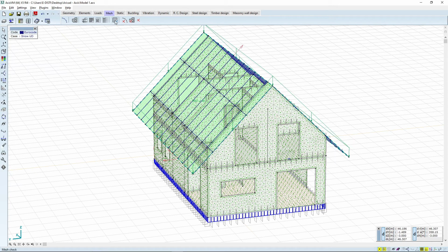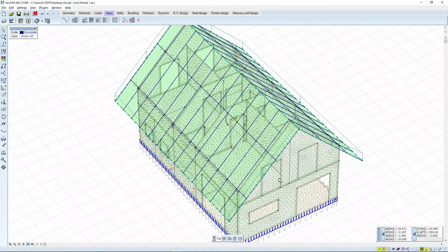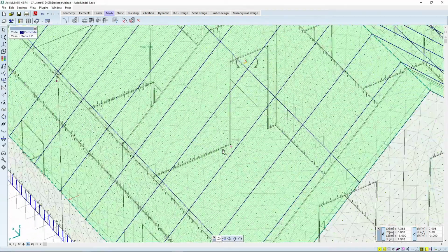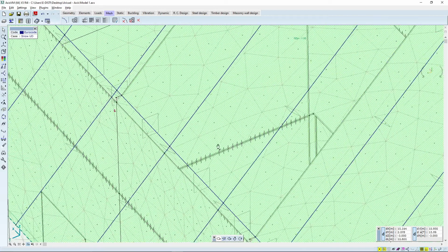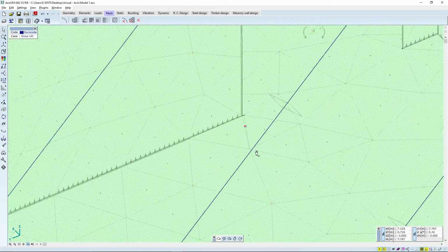We may also check the mesh. So we have 7,405 elements, and 6 of them are heavily distorted, so this is a good number. This means that only 6 of the mesh elements are a bit oddly shaped, so we can even see where this is. It is here and here, and it is mostly okay.